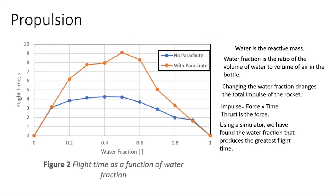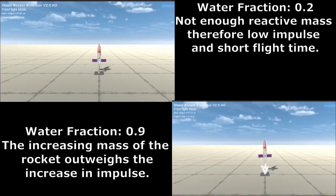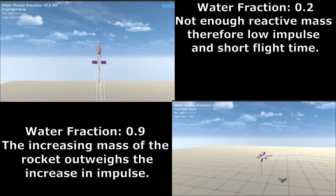Water fraction is the ratio of the volume of water to the volume of air in the rocket. Changing the water fraction changes the mass of the rocket and the total impulse that can be produced. The simulation in the top left is a low water fraction and therefore not enough reactive mass to produce a sufficient impulse for a longer flight.